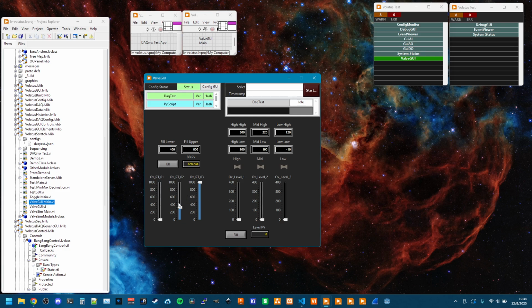This is real nice because you can have one pressure transducer kind of just go off and do its own thing, or a line gets cut or whatever. Some PTs can fail at cryo temps unexpectedly, but the redundancy is nice because as long as two of them are within range, you still get decent values. And you don't immediately lose sight of what your system is doing. And then something very similar here on the right side. So this is just another median triple, not pair.